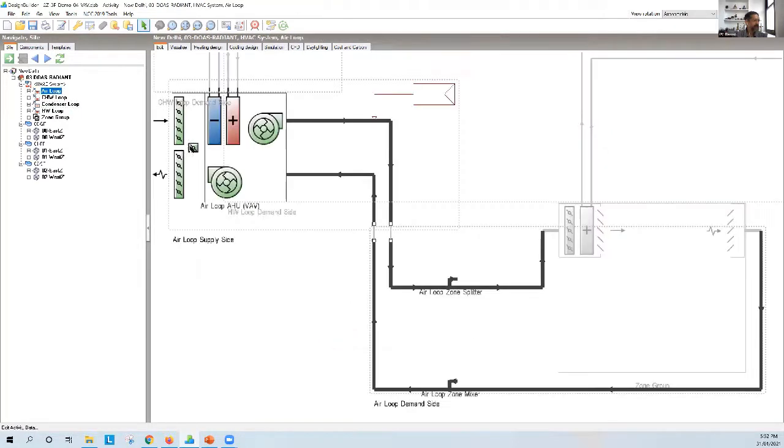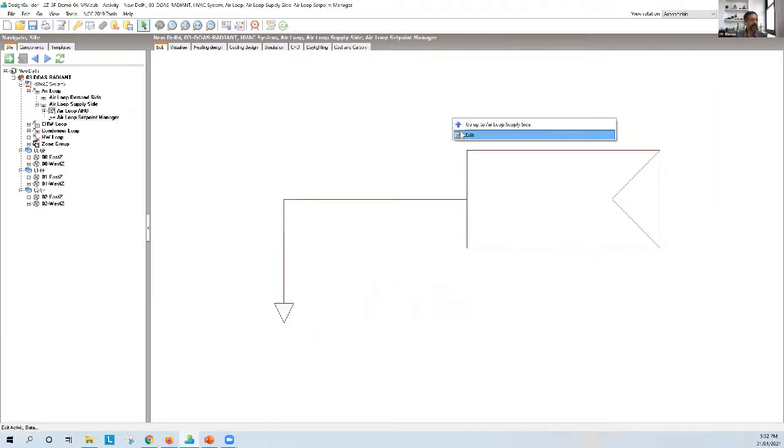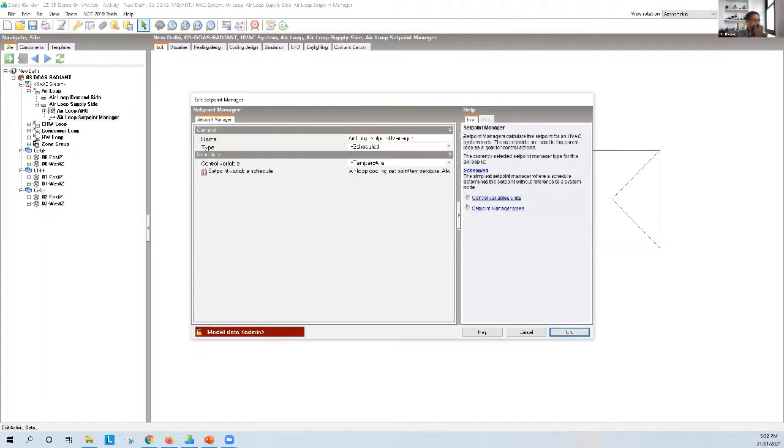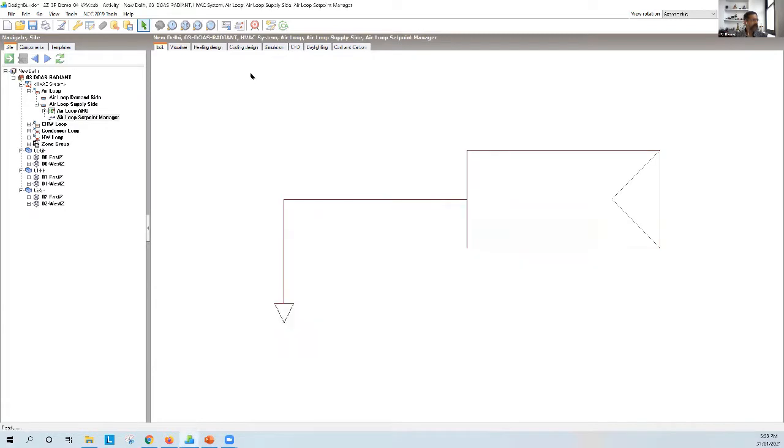I think, let me just see what the air loop's doing. So here's my air loop. Okay, because we're a VAV system, we can actually use something called warmest. And what that means is that it'll try and pick a temperature that gives it just enough cooling to keep the space under conditions. Okay, so I'll leave that for the present and go from there.